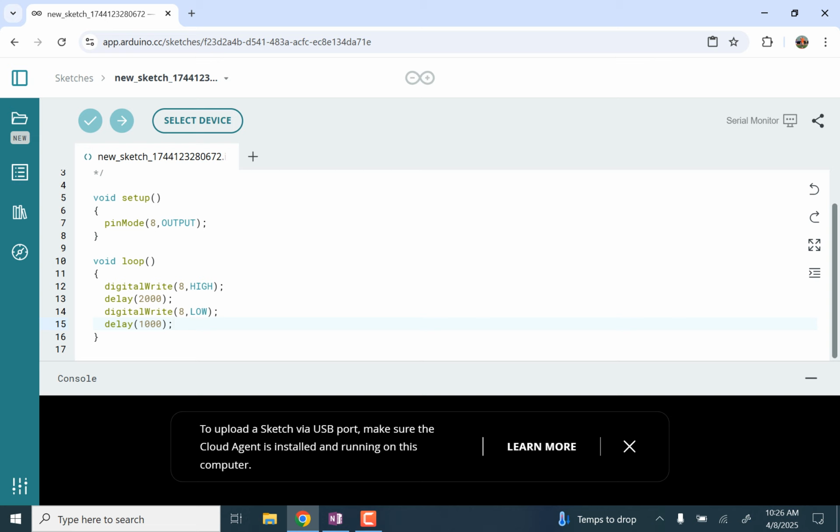Once you have this programmed, go up to Sketch, I think. The word right above there. Sketch. All here? Yeah. And go Verify, Compile. And if there are no mistakes, you'll have to give it a place to store it. Give it some name, Blink LED or something. Blink 182. And click that, and it says that it's done. And so in that case, it worked fine. I think some red errors will pop up if it doesn't compile correctly, but yours worked fine. So let me know if you do that and there's an error.